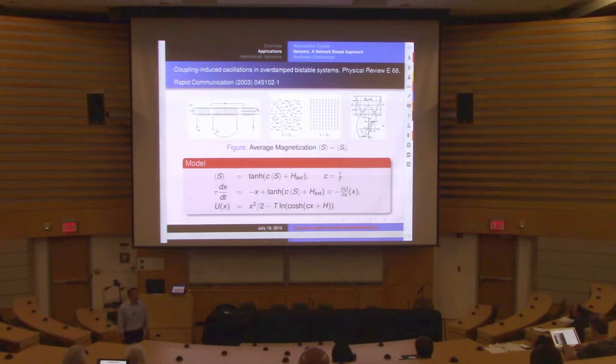So we started looking at fluxgate magnetometers, because they're very, very simple to construct. A fluxgate magnetometer is made of a ferromagnetic material, like this one right here, and it has two coils. In one coil, you excite the system into saturation, you create a hysteresis loop, and then you induce the oscillation. So one coil is the excitation coil, the other coil is the pickup coil, where you pick up the actual oscillation.